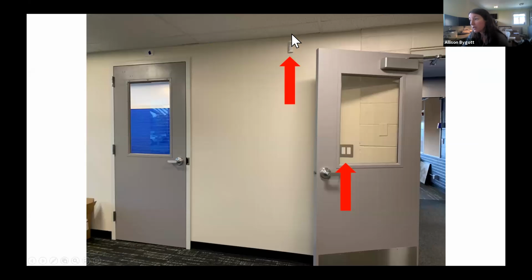So when you look at it, you can't tell if it's on and if it's associated with the lights. The only way I can do that is to either turn on all the lights and leave and wait for the timeout and make sure they turn off, or through an app, I can flash the zones. I might be able to dim the zones. And that is one of the only ways that's really easy to test it. The other way you can test this particular device is if you have a fancy green laser. There's a teeny tiny hole in the bottom, and I can activate the device by shining this laser in the hole. It's kind of hard to get it lined up correctly.